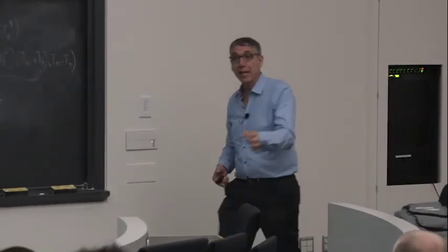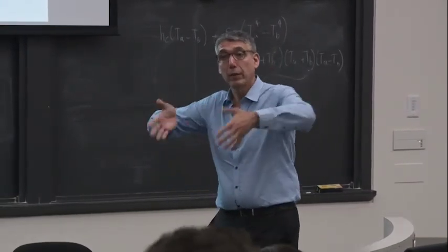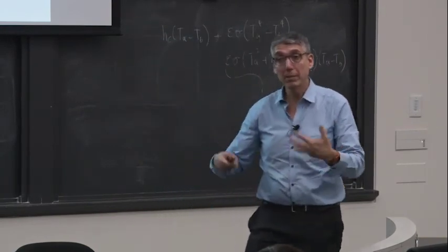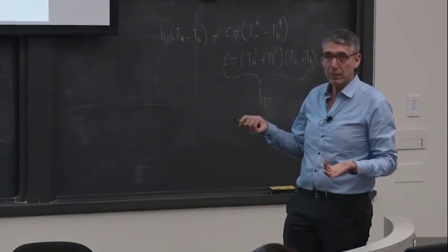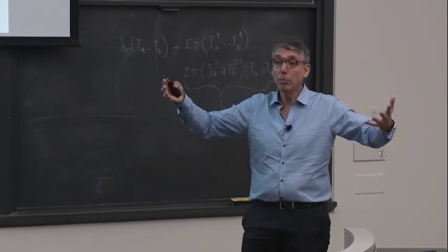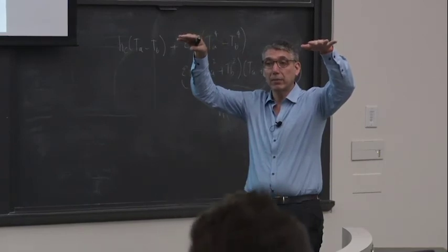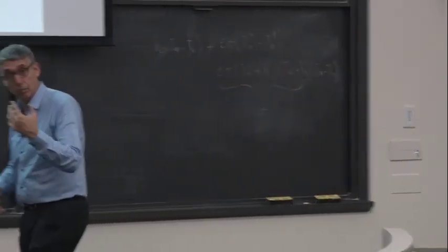Is that okay? Yeah. Maybe relate the heat release rate to the smoke production rate. Yes? And somehow correlate them together over time. Yes, but the question will be, what will be the purpose? So if the purpose is to dimension your smoke management system, in other words, you need to calculate how much smoke you're producing so that your fan can extract it, because you're going to have a very long period of time while the smoke layer is descending. Using an average might be appropriate, because it doesn't matter what is happening at this point in time or at that point in time. What really matters is what happens on average through the whole process, because I'm sucking smoke at all periods of time. So at some point, if the heat release rate goes a bit up, then maybe the smoke layer descends a bit faster, but then afterwards it will slow down. So effectively I can compensate the two. So if it's for smoke management purposes, an average might be probably appropriate.